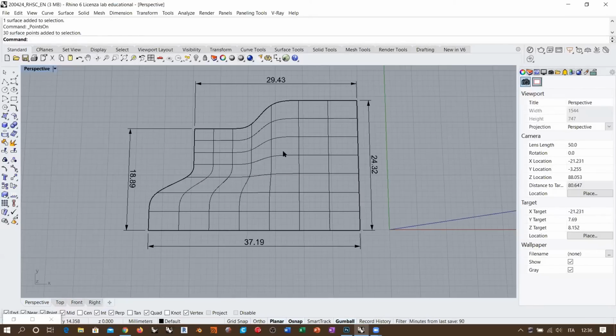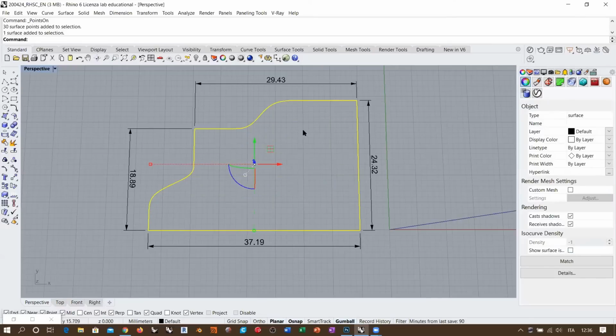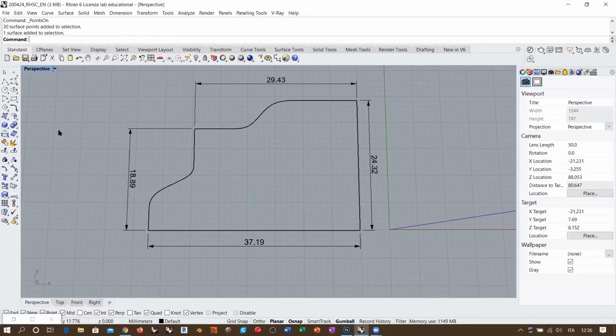This is the reason why, if I, for example, don't consider the actual visible knot lines, and take an extract isocurve command for this surface, you see that the left side is moving slower in this area, and then it begins to move at the same velocity, okay? Therefore, you have this deformation. And as well, if you toggle the direction, you will have this deformation occurring because this area is slower than this area here at the bottom, okay?